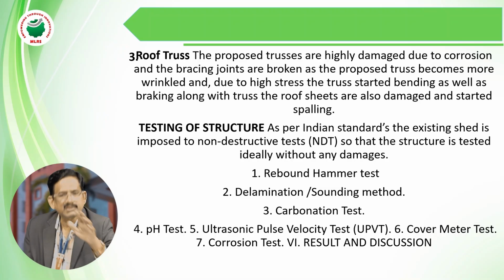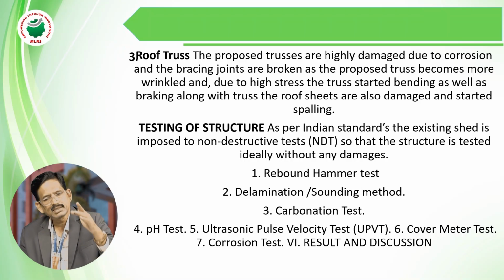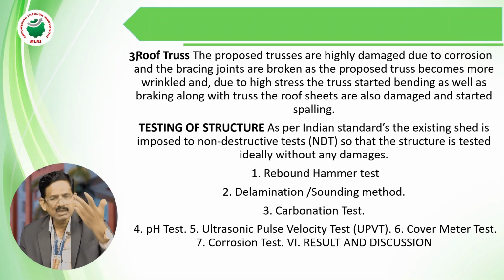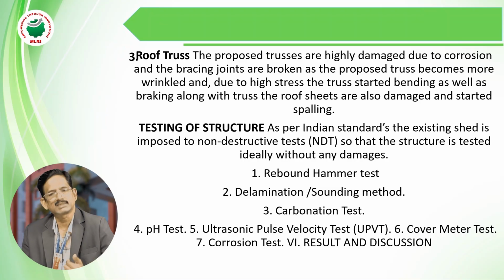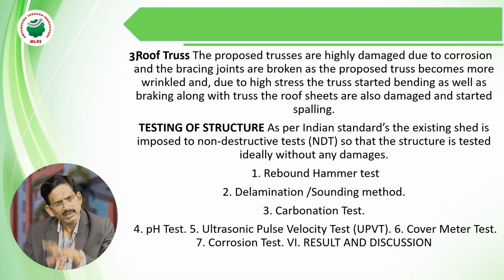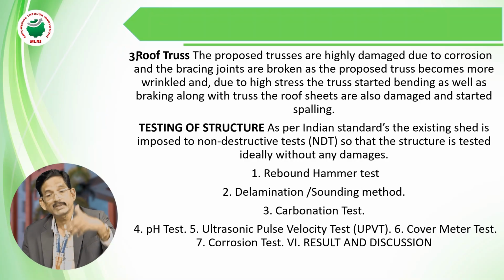If you deviate on all these things, the removal of the props, either of slabs, beams or columns, for a quick completion of the project, and you don't follow the standards, automatically you have to reduce the strength itself. So instead of M40, you go for M30, you reduce the compressive strength of the concrete by 10 newtons per mm square. Instead of 16 mm, you are going to use 12 mm. Instead of 20 mm, you use 16 mm. Instead of 25 mm, you use 20 mm. So these are all the deviations, these are all the differences with respect to the design.